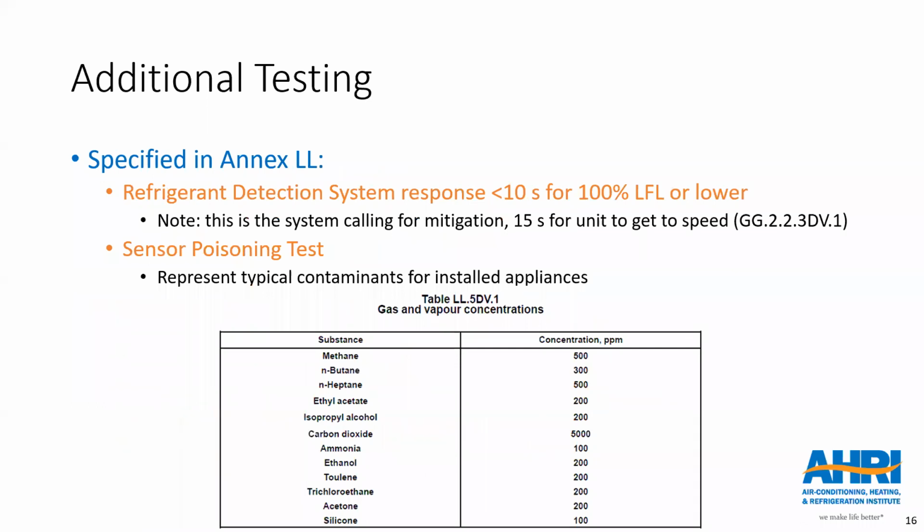So as I mentioned, there was some specific testing required for Annex LL. And one of those tests is the response of the overall refrigerant detection system. The requirement in the standard is that the system responds in less than 10 seconds when exposed to 100% LFL or lower. Now, once again, I had mentioned before that this needs to be done over the entire temperature and humidity range. But the sensor itself, or the refrigerant detection system itself, needs to respond in less than 10 seconds. And that's calling for cooling.